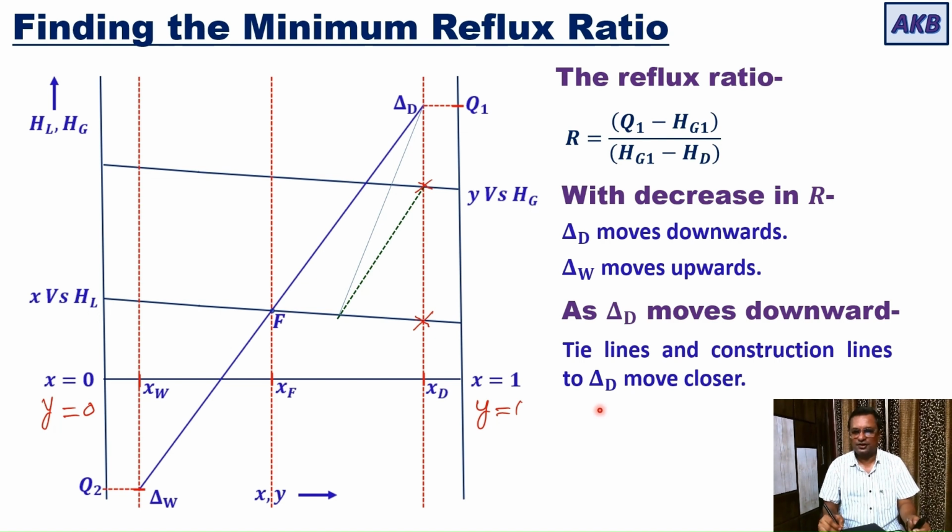Decrease in the reflux ratio. The construction line, I hope it is visible to you, the blue line that I have drawn, moves closer to the equilibrium tie line.